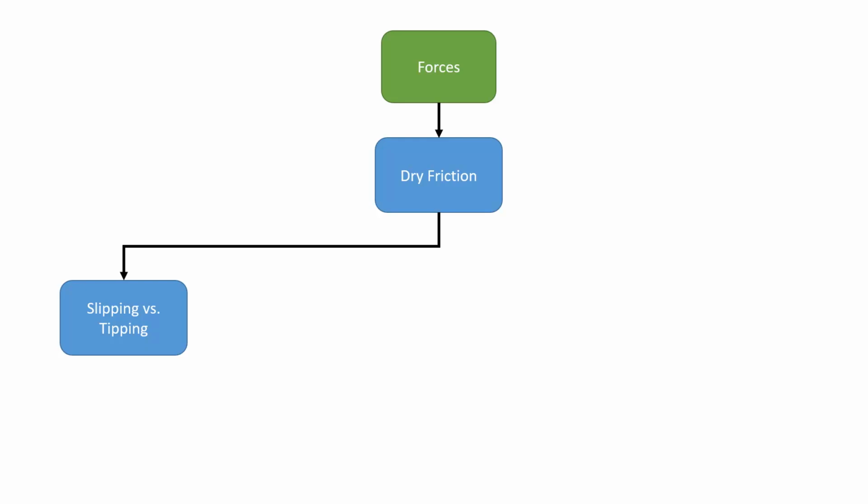At its core, that is a question of comparing the friction force, which is part of this, as well as the couple that we're going to get from the weight force and the normal force. And if it's a large enough couple from the friction force and the pushing force, we overcome that other couple and we're going to have the object tip over.